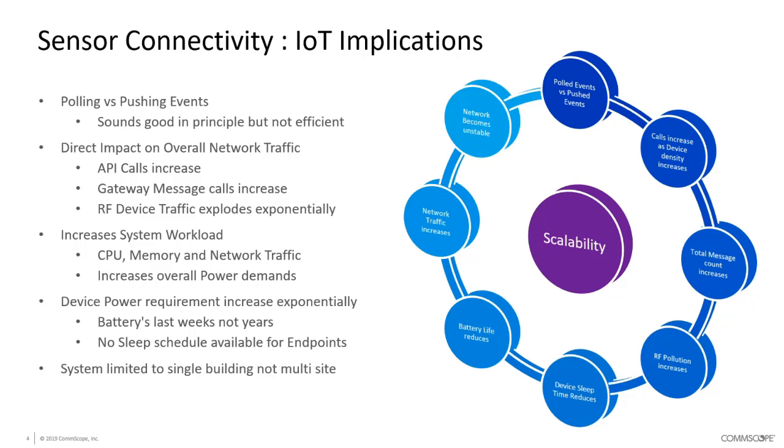A lot of the way that IoT devices become very battery efficient is they sleep for 90 to 95% of their time. So if there's nothing going on, they are asleep, they're not transmitting, there's no processor running, everything is really shut down. That has an impact on latency as well as battery life.